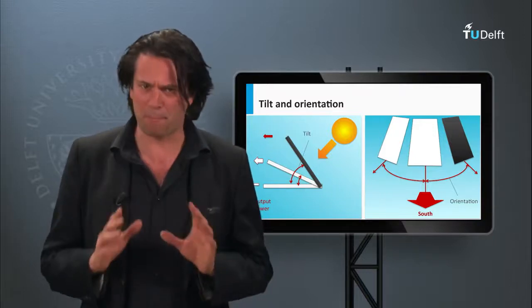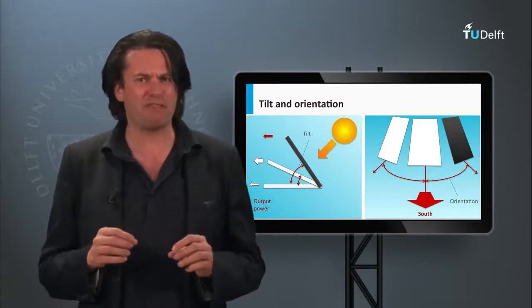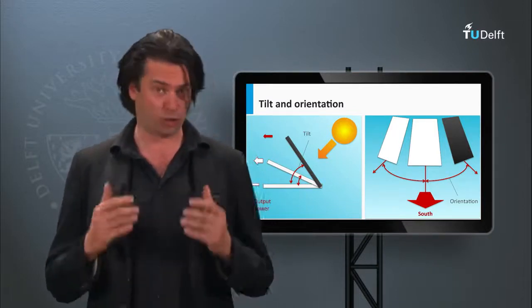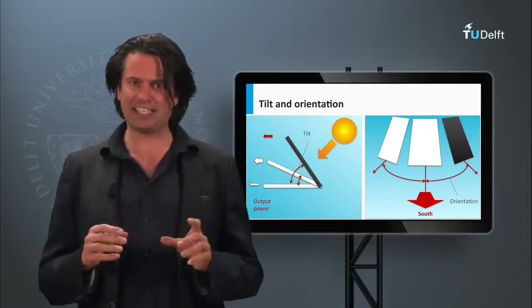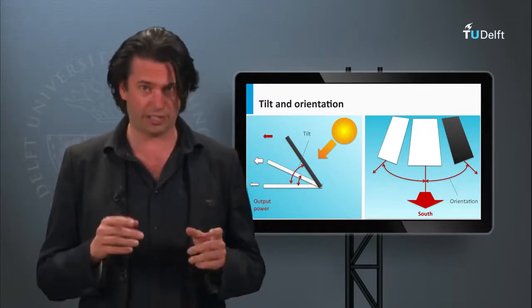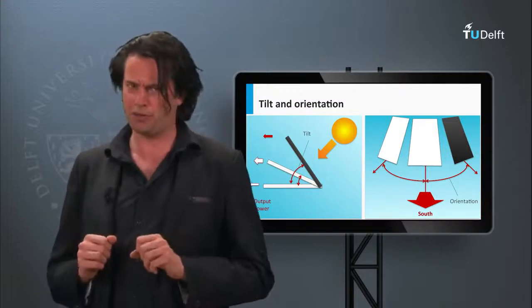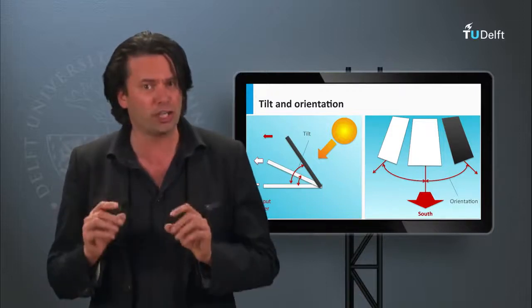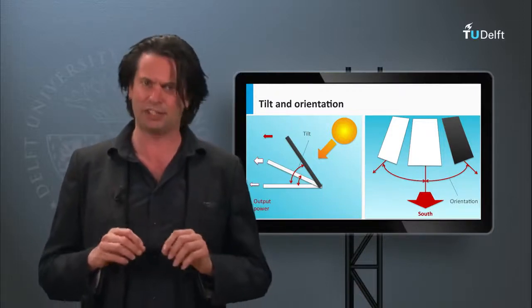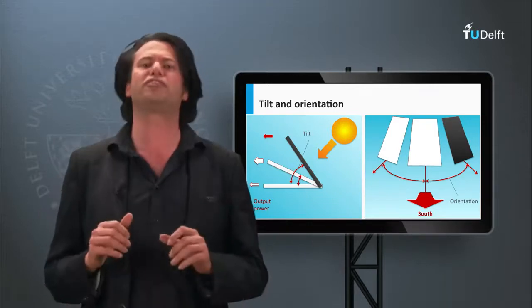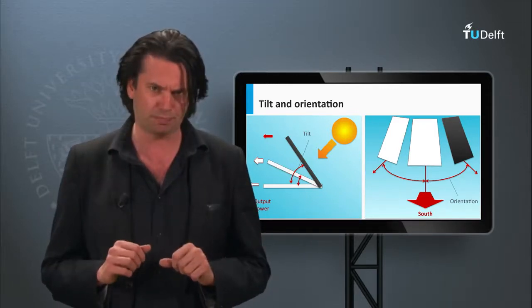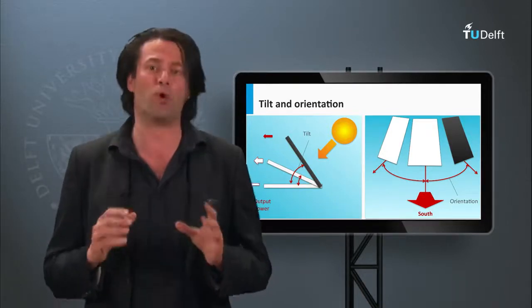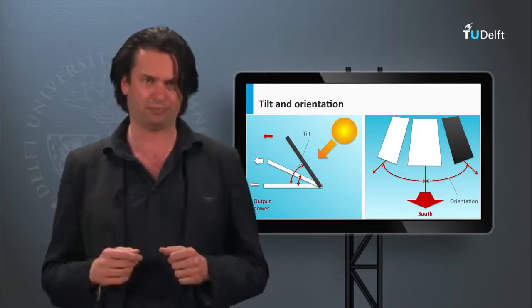It has been seen in practice that optimized angles can give up to 70 to 80% of the maximum PV yield. As long as the solar panels are facing in the right direction in general, that is, facing south for a panel in the northern hemisphere and north for a panel in the southern hemisphere, it's usually observed that the variation in the optimal orientation angle doesn't vary the PV yield much. Consequently, the optimal tilt of the panels help in saving more energy than the optimal orientation.